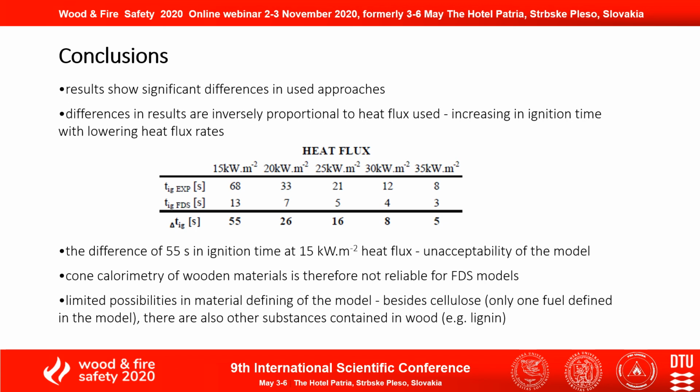According to gathered outcomes, we can see that in this case, the FDS model doesn't correspond to the laboratory experiment. Reaching the difference of 55 seconds in ignition time at 15 kW per square meter heat flux only highlights unacceptability of the model as a whole. Cone calorimetry of wooden material is therefore not reliable for FDS models.